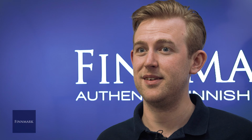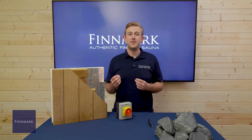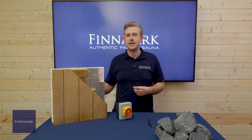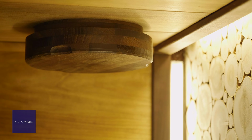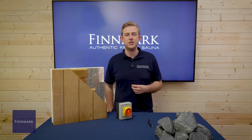However, in most cases, you'll require 2 points of air intake and 2 points of exhaust. The points of air intake could be a gap under the door and a vent low down behind the heater. 2 points of exhaust can include a vent at head height, often referred to as the dump vent or drying vent, which allows the sauna to dry off after usage, as well as reduce any excess heat or humidity if required. The second principal exhaust is located lower down under the benches.